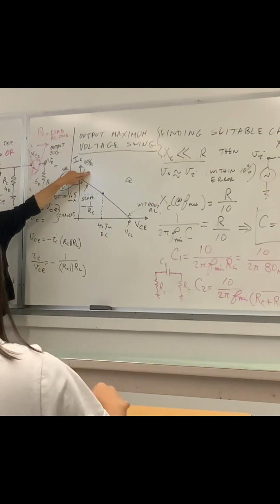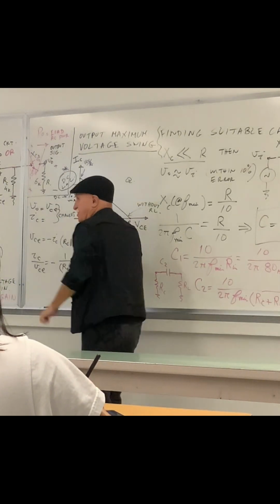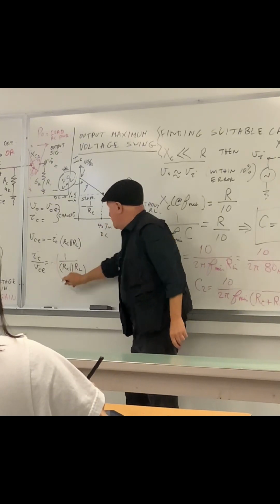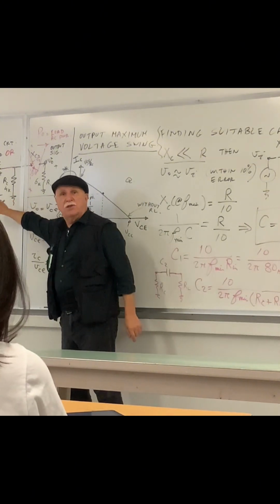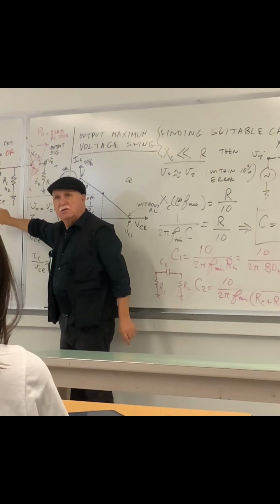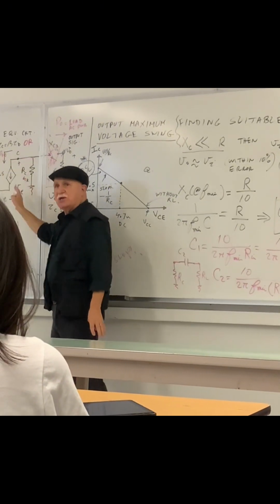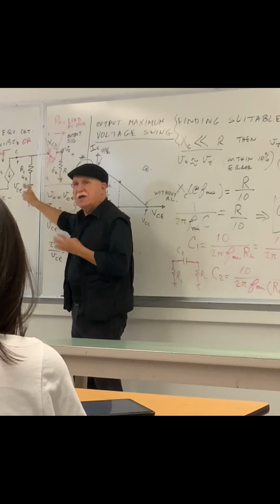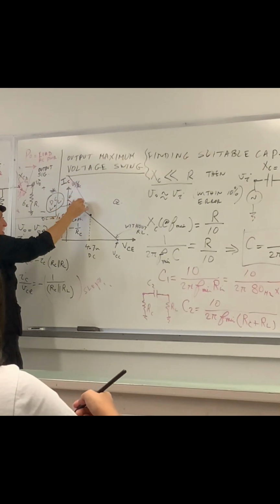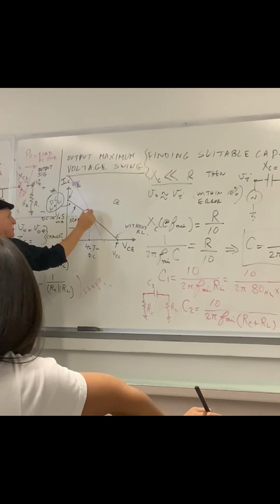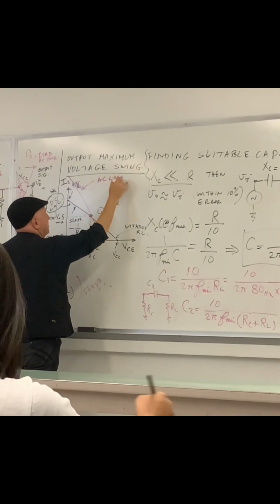Guess what is the slope of the AC load line? And don't miss me right here, the AC load line. That's the slope. Do you see that? Slope coming from the model, from this AC small signal model. Simply, it's the voltage across this branch related to the current that is injected to both RC and RL, which is this line, gentlemen. There you are. This is known as the AC load line.